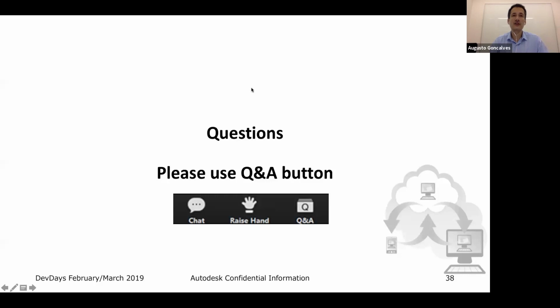The next one is, there is no UI functionality at all. Yes, there is no UI, absolutely not. You cannot use anything that interacts with the user. If you try to do so, the engine will just return failure, or even halt and wait until it times out. So if you ask the user for input, the system will not work. This is very important. Remember, it's a batch operation. You pass the input, pass the sequence of commands that you want to run, it will run, and you get the output. That's it. There are no interactions with the user.